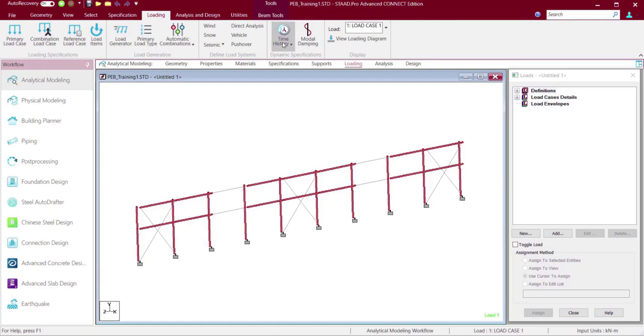Okay, so we are subdividing into two different sets of panels. Now here you can see I have selected three different frames, but my assumption is that in between these selected frames there is an opening, because we are assuming that in this factory shed, for example, on this face there would be some gates or doors and this would be kept open.